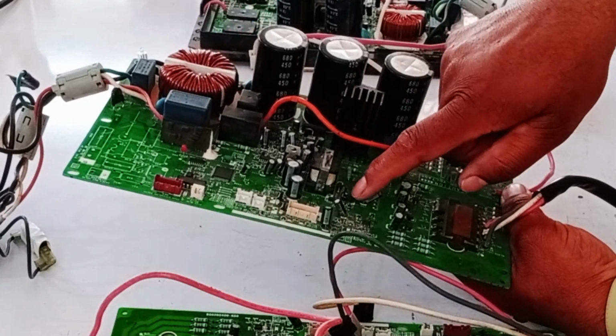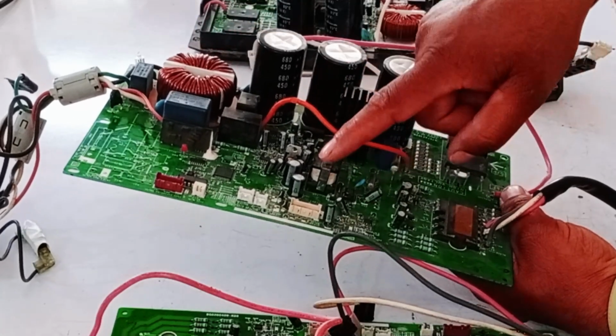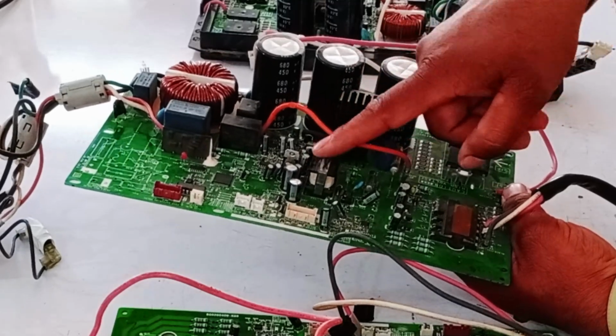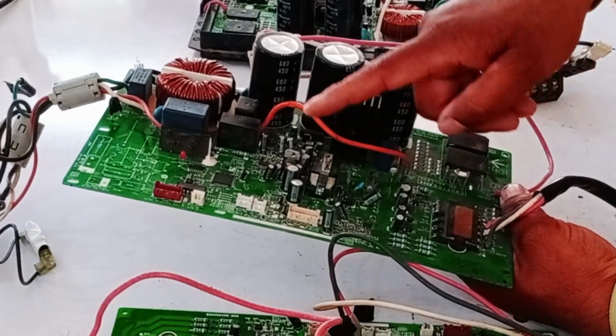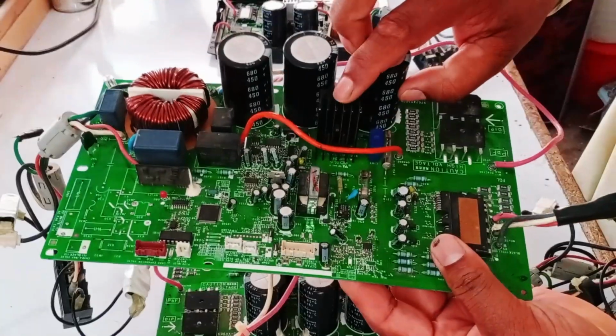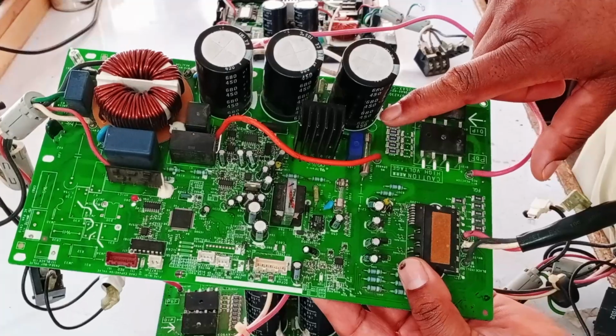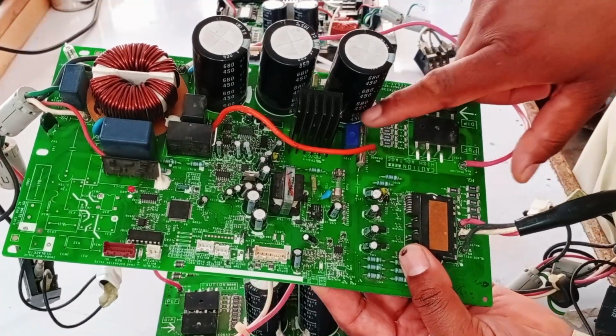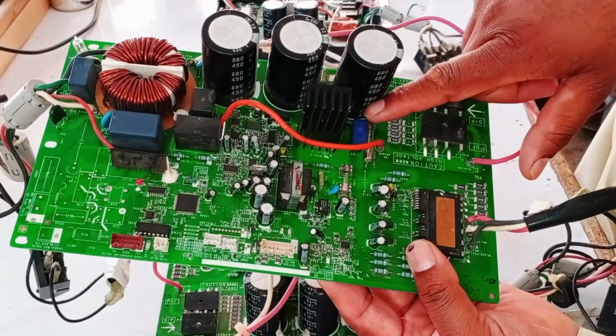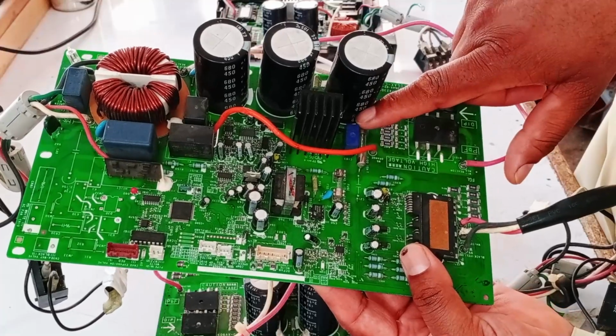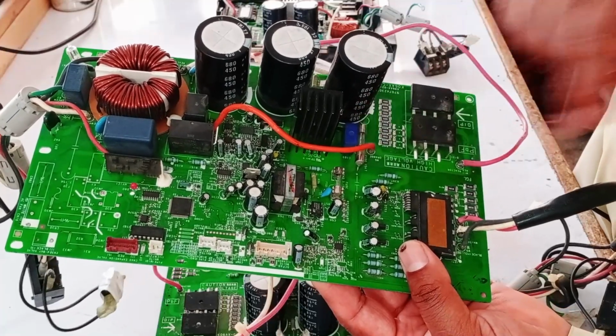1. Switching IC. This can be faulty, so it should be checked properly. 2nd, chopper transformer. This component might also be defective, so inspect it carefully. 3rd, IGBT. Check this component to ensure it's functioning correctly. 4th, fast recovery diode, D102. This diode is often faulty, but it may not always show as defective during testing. Replacing it usually resolves the issue, so it's a good step to take.